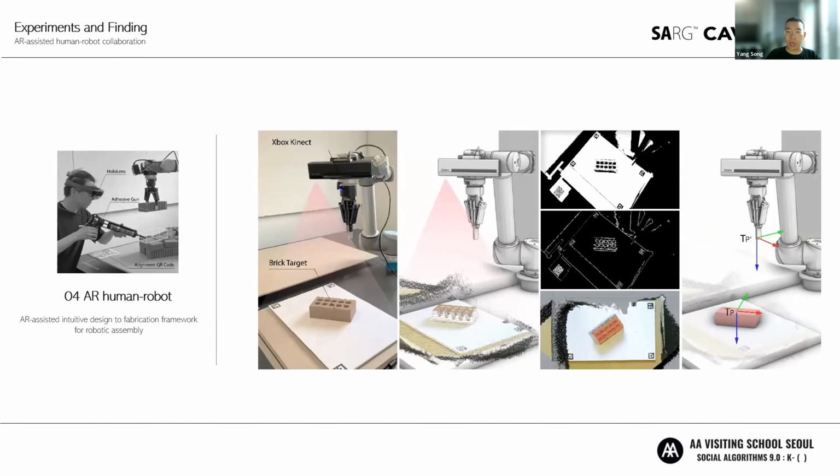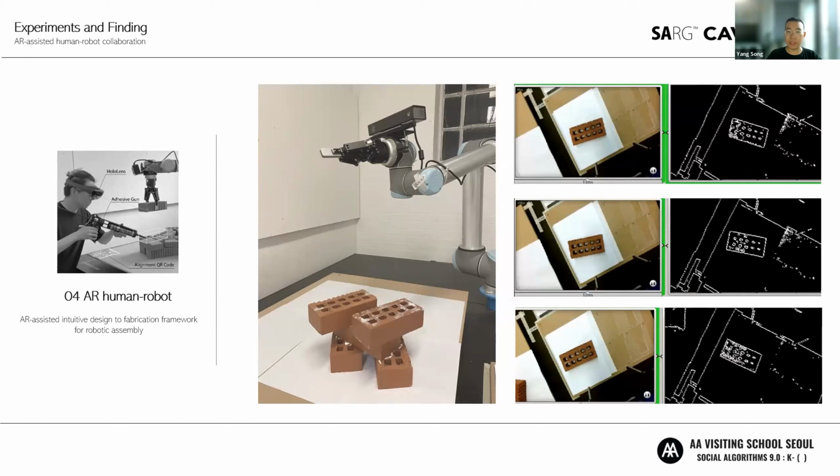So we created a target location recognition system using the Kinect sensor RGBD camera to scan, recognize, and also analyze the brick location, which needs to be picked in real time. So this method frees the automated brick laying from a fixed brick feeding location and also the installations, and provides a more flexible on-set brick feeding method.